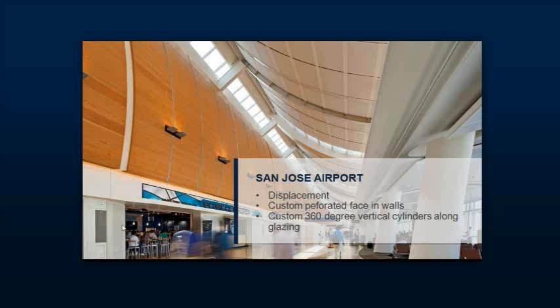Another example, I guess, actually, is the San Francisco Terminal 2. When they renovated this, they actually found a 20% energy savings above and beyond what Title 24 required in their buildings using displacement. And you can see in the back corner of this room the displacement diffusers that are integrated here. And they were sized and shaped such that you get this interesting pattern of lines that's actually discrete diffusers.